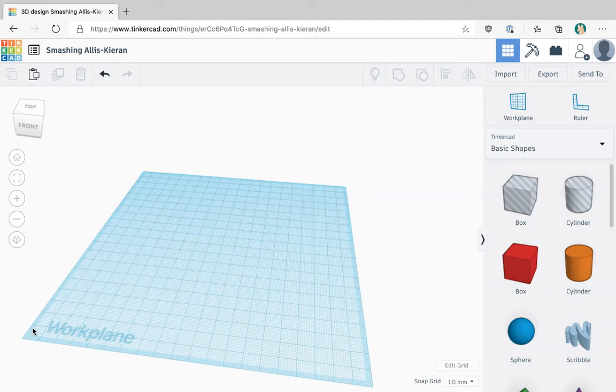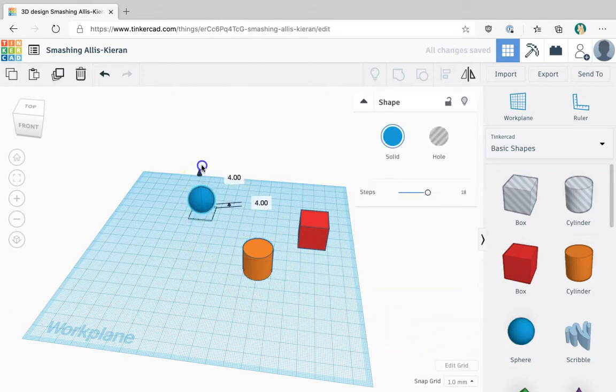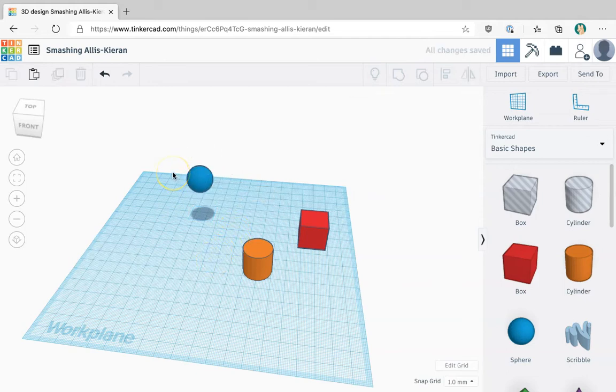It makes it easy for you to align multiple objects along a common plane. And we're going to try it out with simple shapes, a box, a cylinder, and a sphere, but you can use align for basically any shape out there. I've placed them pretty randomly, and I've lifted this sphere up so that nothing is in alignment. And normally if you wanted to place them along the same line, it would take a lot of time and energy because you would have to drag them and you would have to align them with your eyes, which is difficult. So this is where align comes in.